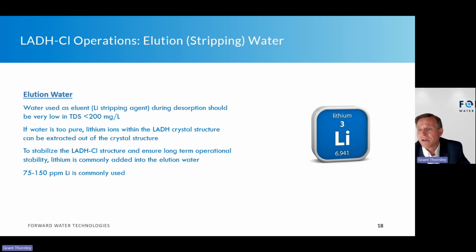And it's easily seen when you're doing your testing. Do a mass balance. If you're finding that, okay, my brine is, let's say, 100 ppm, and when I finish my recovery I'm getting, let's say, 110% recovery, or 110 ppm coming out the back end.